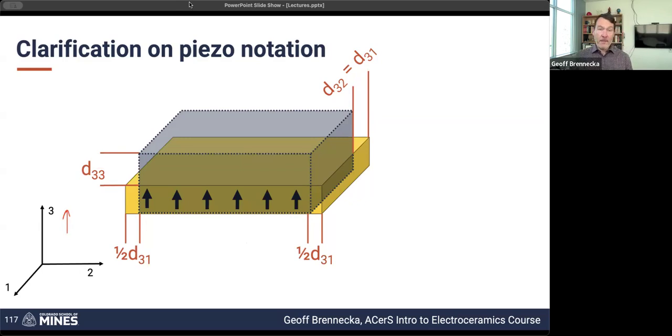So that's what this refers to: if we're applying the field or applying the strain in the same direction as poling and making the measurement of the other one in that same direction as poling. Alternatively, and we talked about Poisson's ratio last time, let's say we apply a field in the three direction, we're going to get strain in that three direction. We're also going to get a shrinkage laterally. That's the one direction. It's actually one direction and two direction. So this would be two, that's one. Again, just by convention. Those are going to happen whether we like it or not.